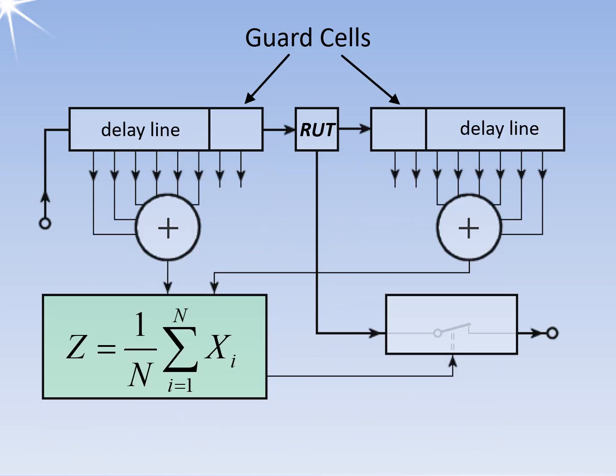However, due to the geometric expansion of the reflecting object, an echo signal is often larger than this one range cell under test. In this case, the edges of the echo signal would be deformed by the circuit. This can improve the contrast, but it would also mean a loss of information. Therefore, the immediately neighboring cells are often not used to calculate the threshold. These cells are then called guard cells. This precaution is not necessary for statistical methods such as OS-CFAR or CASH-CFAR.